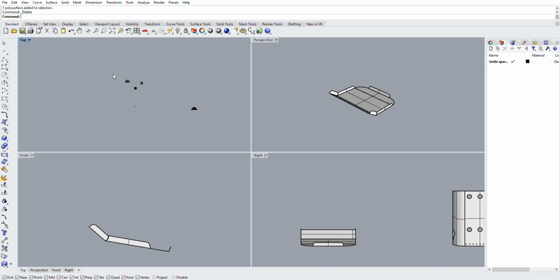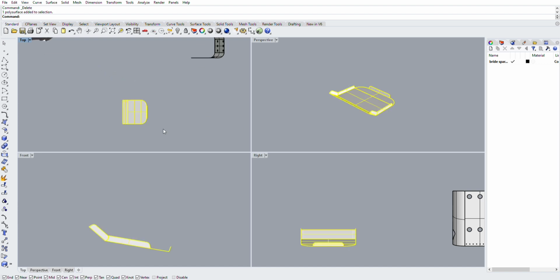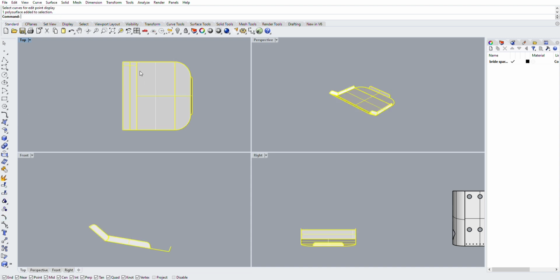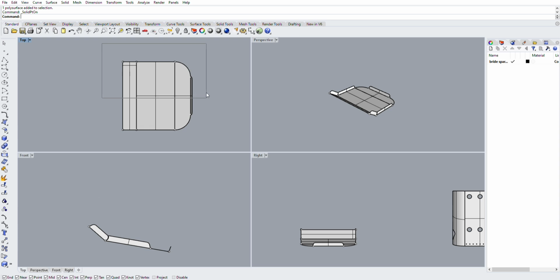So, oh, what have I done? Oh, I know what I've done. Since these are surfaces, there's no thickness to them. Now my flanges are going to bend up from the edge of that material. So I know that if I'm building this out of 1/8 inch for the sake of argument, that I need to bring these in 1/8 inch for this material to come in.